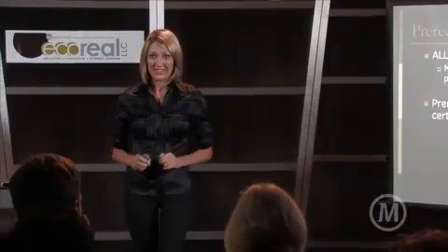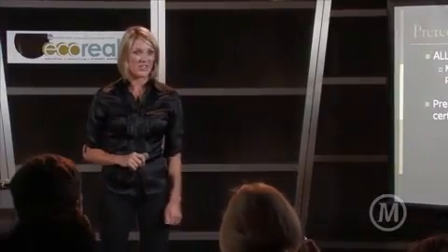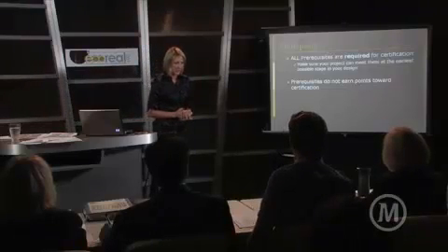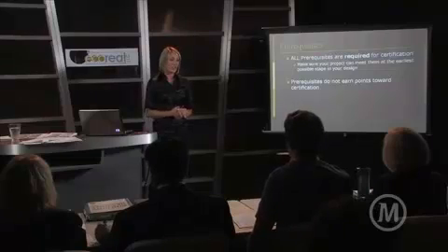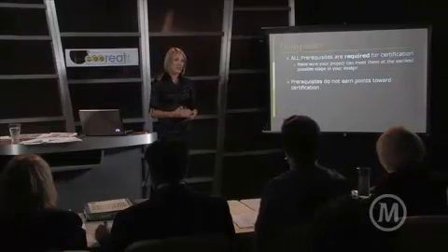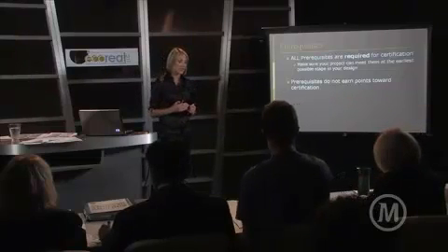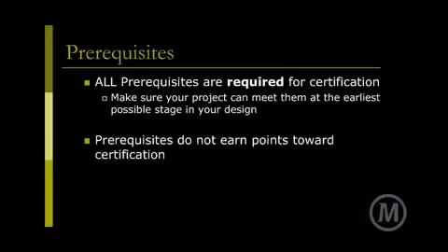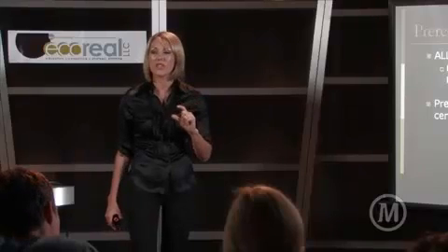So prerequisites, a little terminology since we're throwing these terms out here. These are the mandatory things that you have to hit within each category. And now each category within the LEED rating system for building design and construction has at least one prerequisite associated to it. Water didn't used to have one. Now it does. That's responding to the needs of the building industry and taking a look at where our resources are at. And water now, there is a mandatory 20% savings.